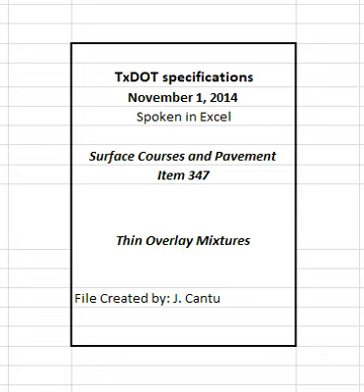The location of the engineer's blind sample will not be disclosed to the contractor. The engineer's blind sample may be randomly selected in accordance with Tex-225-F for any sublot or selected at the discretion of the engineer. The engineer will use the contractor's split sample for sublots not sampled by the engineer.